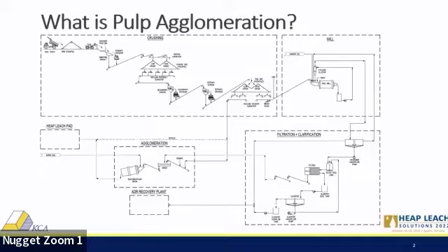So the ore was crushed. The low and high grade ore was crushed in a shared conventional crushing circuit. At Castle, they used a gyratory crusher. Here it showed as a jaw crusher. The high grade ore was then milled in a single stage. The milled material was then thickened, followed by filtering.